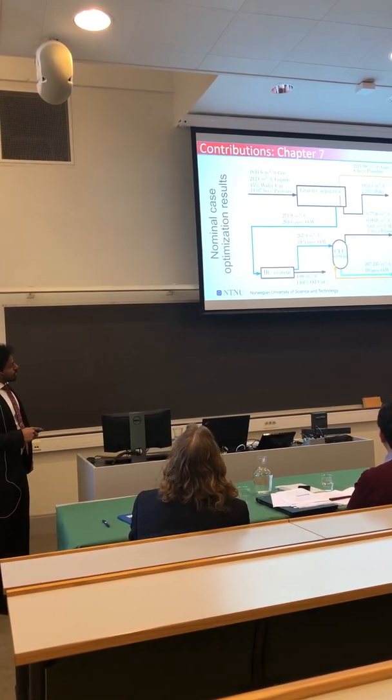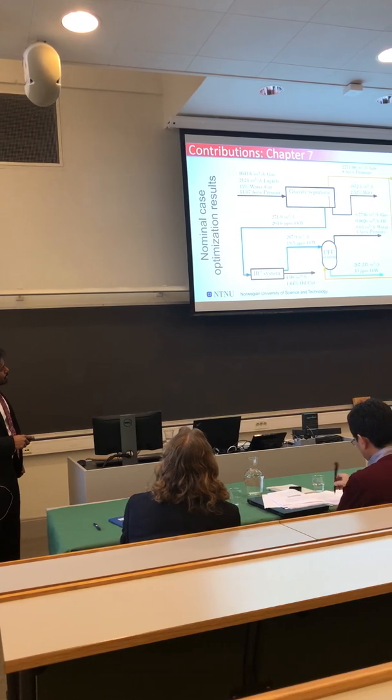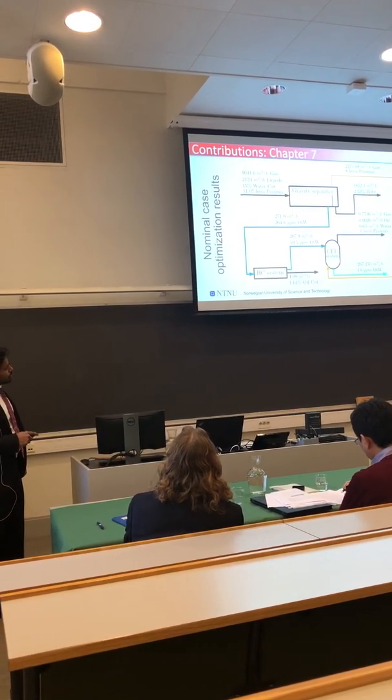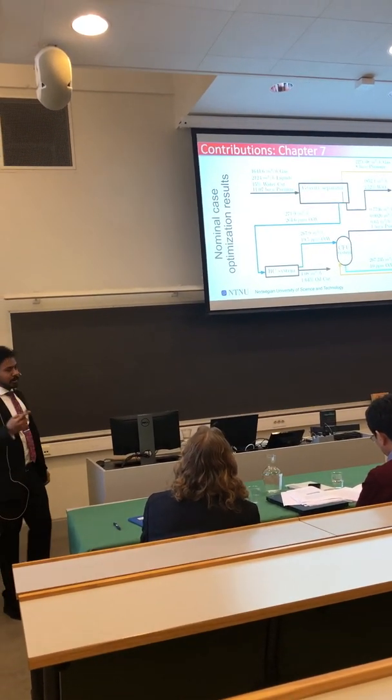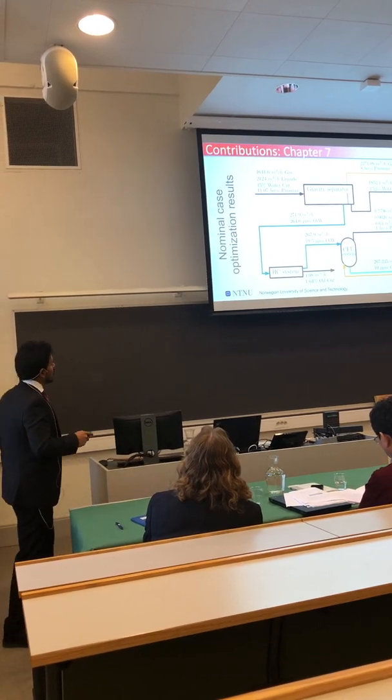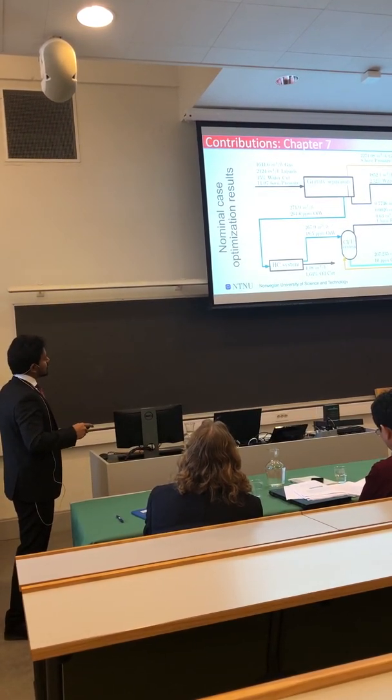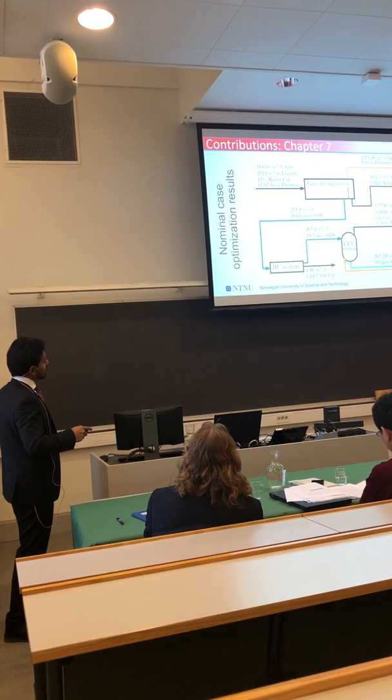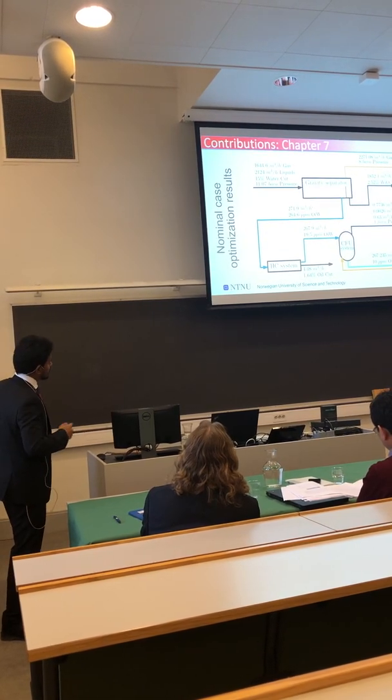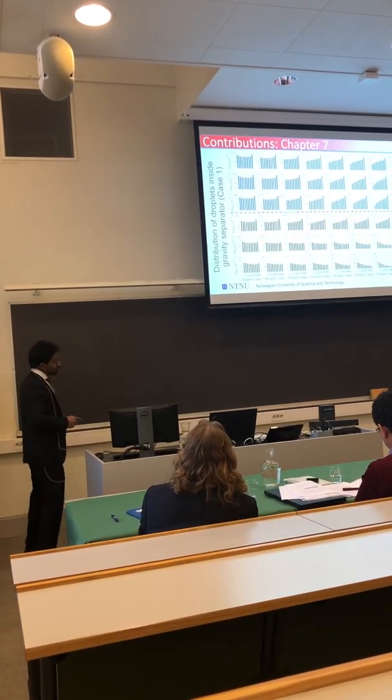Then we have the CFU system. In the CFU system, we finally reduce it further down from 19.5 to 10 ppm and make it suitable to throw into the sea. The rest is going at the top, which is the reject stream, which has maximum gas, a little bit of oil, some water, and it is at 1 bar pressure.